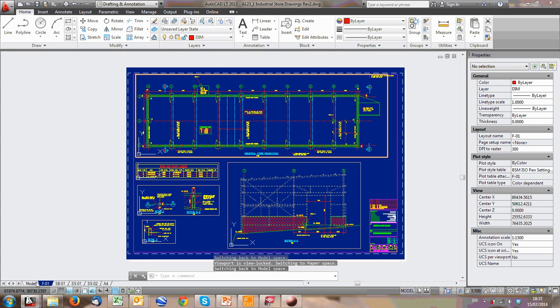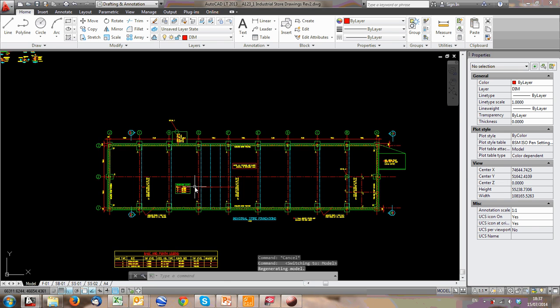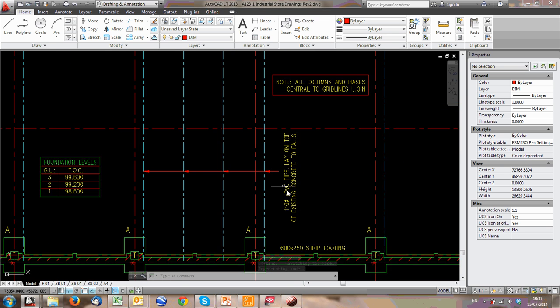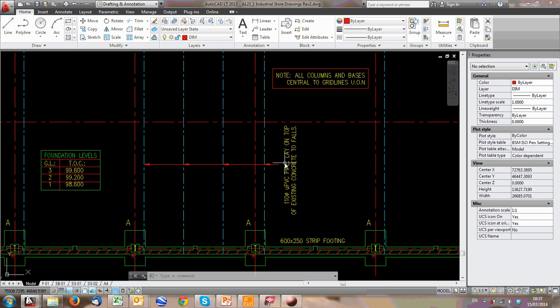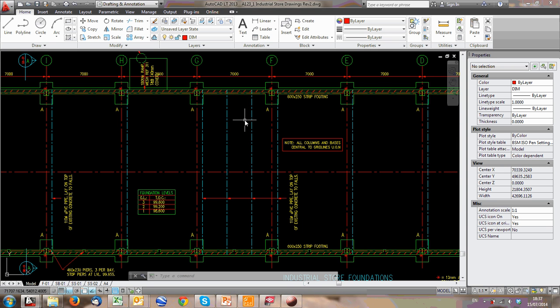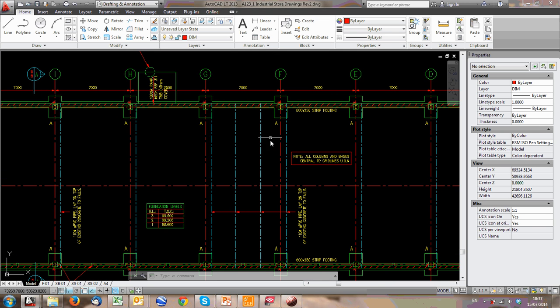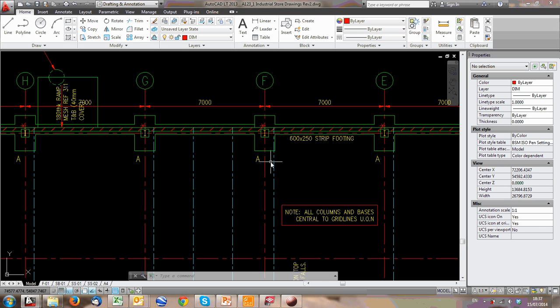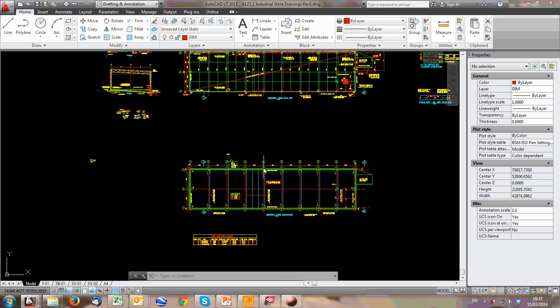Right, now back into AutoCAD, and back to our layers. Alright, so that was our foundation layer. This one also showed other things that went in. These were drainage lines that went underneath the building, those cyan lines. If you have anything at the same level as the foundation, you probably show it in your foundation drawing, even if it's a drawing on its own, just giving basic details, just to avoid clashes, so that you don't have the pipe going through the column.